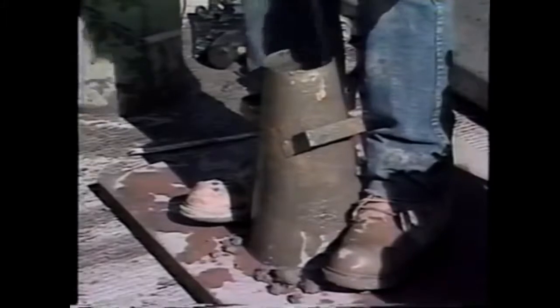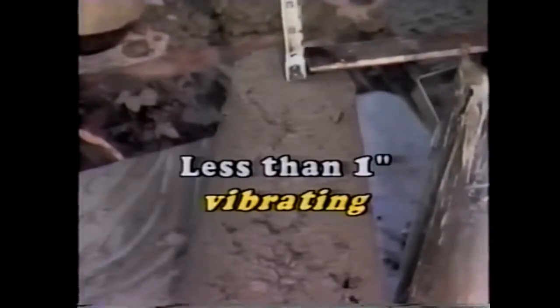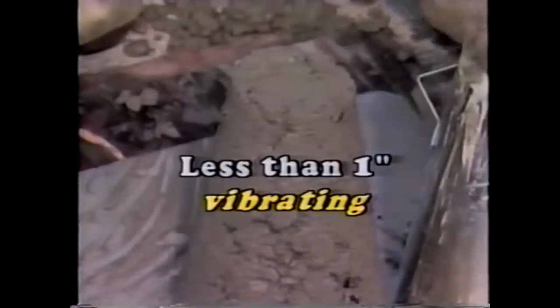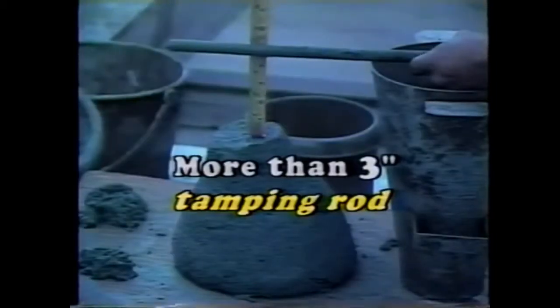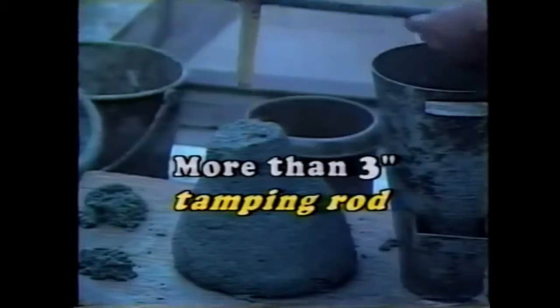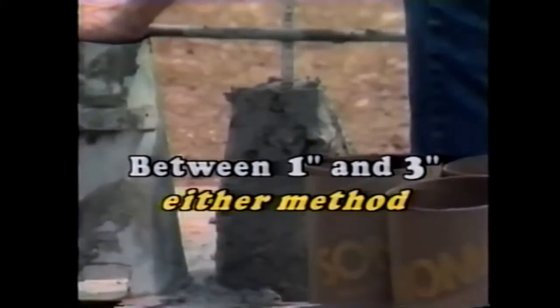And the method of consolidation depends on the result of the slump test just performed. If the slump is less than an inch, vibrating is required. If it's more than 3 inches, use the tamping rod. And if it's between 1 and 3 inches, either method can be used.